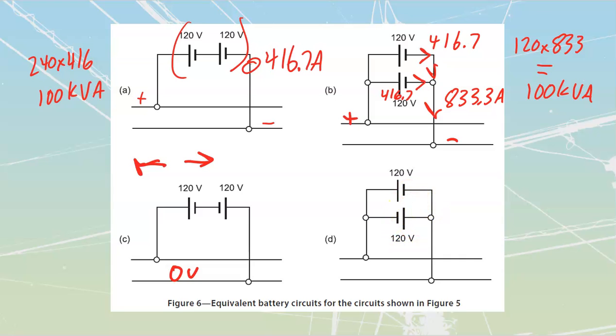This is what it's actually doing over here. If I were to take it and draw it out of the batteries, you can see that I'm going to have current that is going to travel through and through. And it's got absolutely zero interest in going anywhere to the bus. There is no net voltage. If I take a look, I got 120 in one direction, 120 in the other. I'm going to have a net of 0 volts across here, but I'm not even going to get around to measuring that because my transformer is going to be on fire at that point already. So yeah, just watch those connections.